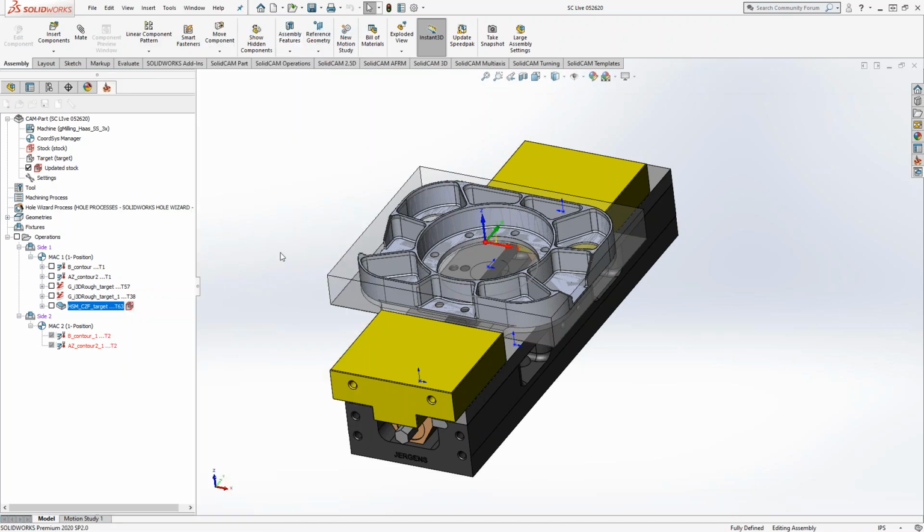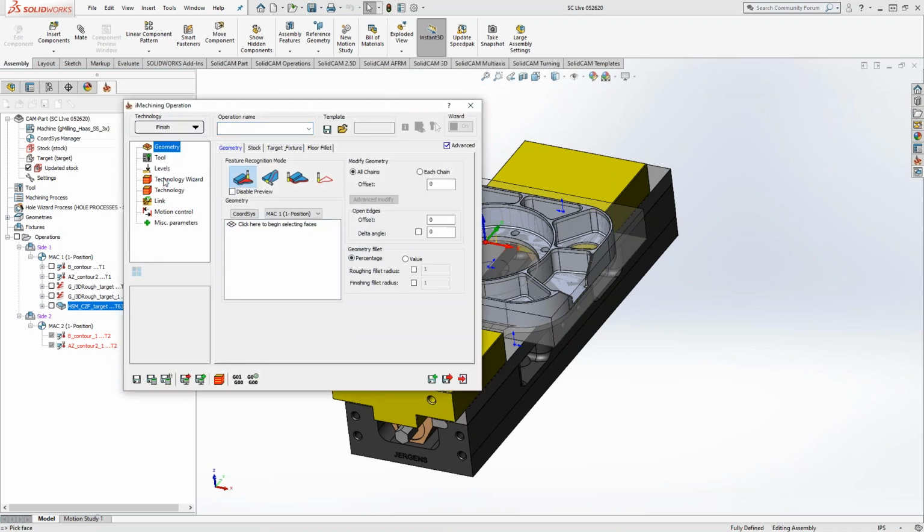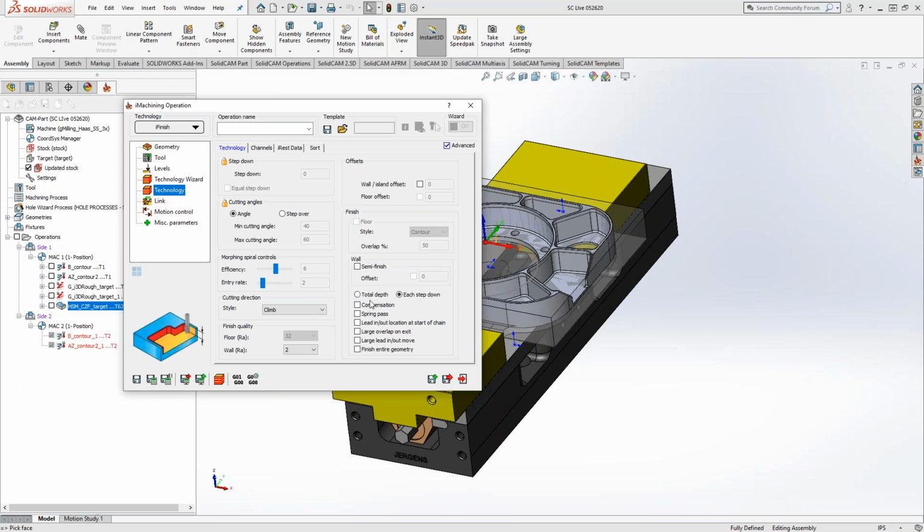So if we're getting into the 5/10 tolerance, plus or minus 5/10, then I would definitely come back, do like an eye finish, because in there we do have the ability to do multiple or spring passes, what it's considered. So it's actually doing multiple passes in there to get that really tight tolerance area. And to answer Edwin's other question, iMachining does have compensation when you're doing eye finish.